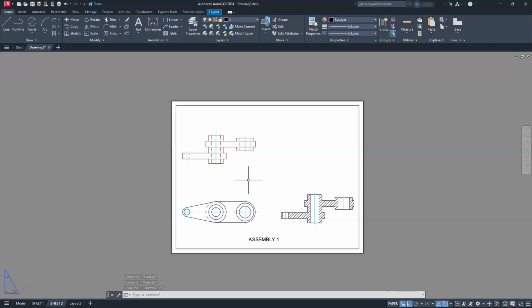Now the other method I'm going to show you here is going to require you to make multiple viewports, but you're not going to have to go and play Jenga with all of your different shapes in model space. So one way is you're going to do it in model space. The other way is you're just going to move things around in Paperspace, right? So that'll be the last thing I show you on this, and we'll probably say our goodbyes for this video for the night.